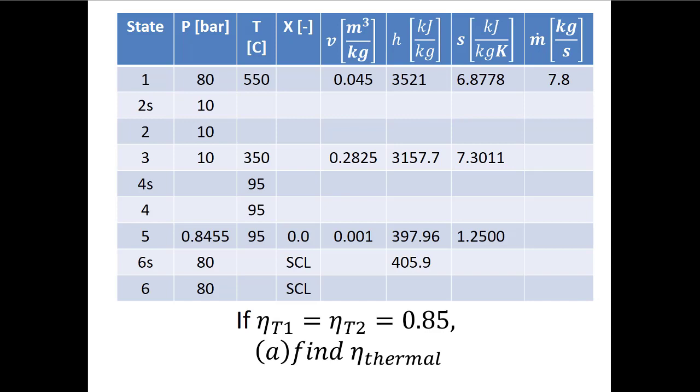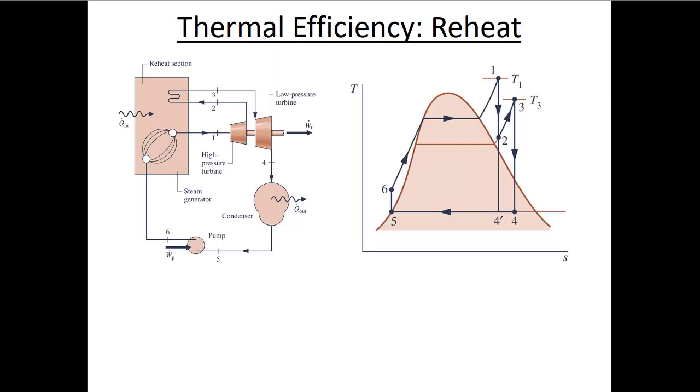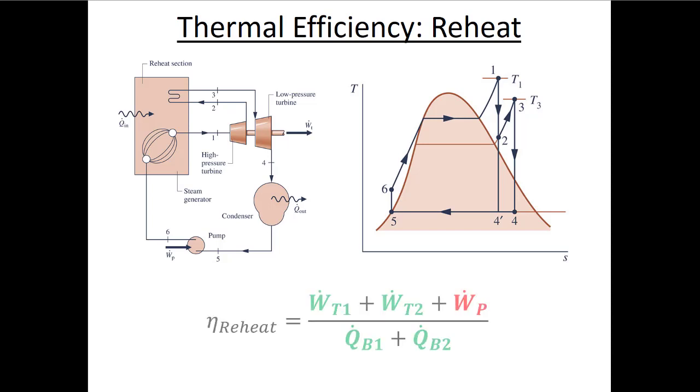Now, the problem is asking me to find the thermal efficiency. So, what is the thermal efficiency for a Rankine cycle? I know the Rankine cycle is a heat engine. The energy benefit is the net power, and the energy cost is the heat transfer rate in.